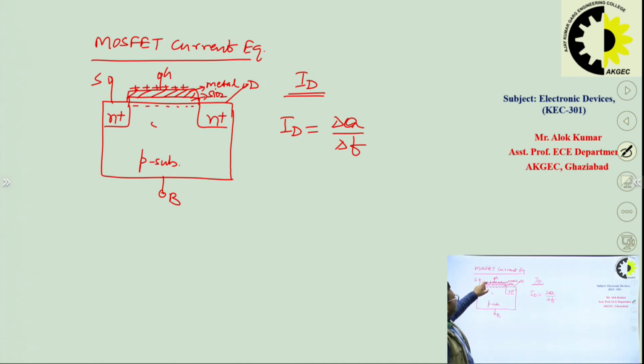And this charge is separated by the oxide and the metal. So, this region is behaving like a capacitor, because we can consider this one plate having positive charge, and below we can consider another plate which has negative charge, and these two plates are separated by the oxide, okay.